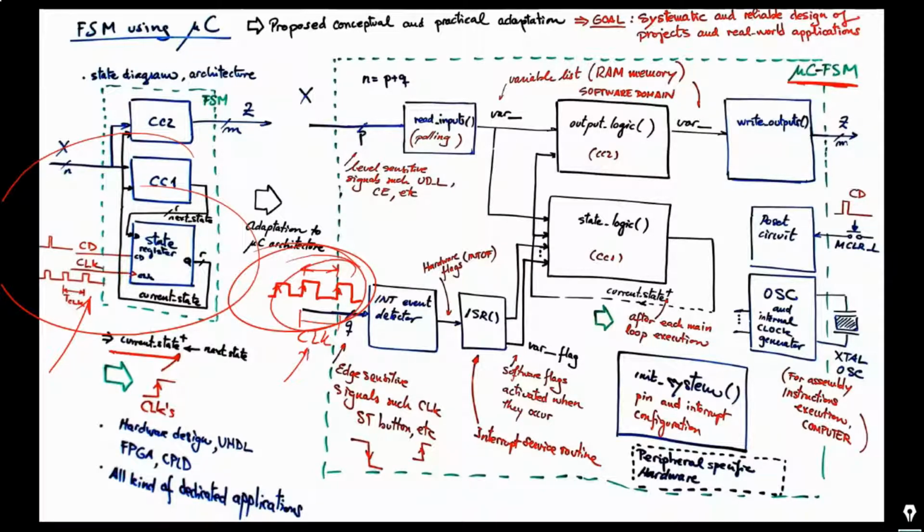External, this time. Or if you are inventing a counter or a timer, you like to go increasing the count number as usual, every external clock rising edge. So you see, in some way, you have the external clock that is for updating the functionality of your real-world application, and the internal clock that is attached to a high-frequency crystal for managing the computer.